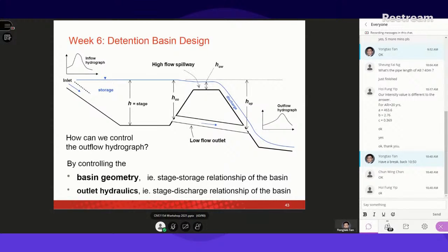Sorry, horizontal. H means horizontal. The horizontal of the detention basin, 1V, where V means vertical. Vertical means the depth of the detention basin. So it means 4 horizontal to 1 vertical, meaning no steeper than this. This is the side slope requirement for the detention basin.